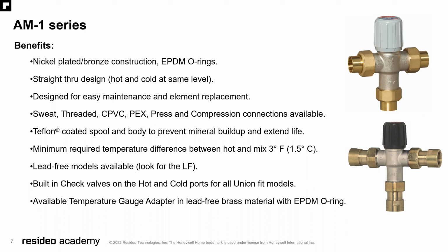We do have lead-free models. Just look for LF right in the model number. Built-in check valves on the hot and cold ports for all union fit models. And we now also have available a temperature gauge adapter in lead-free brass material with an EPDM O-ring. These can be mounted as point of source or point of service. Remember to check the ratings of each mixing valve before installing.